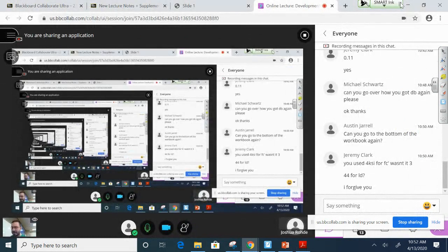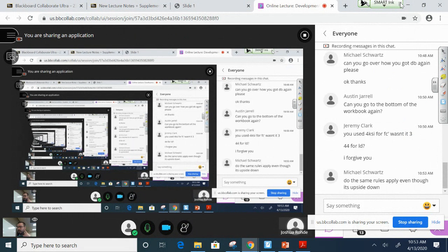What we're going to do next time is, as you noticed, we got a development length of 44 inches. That's kind of long. So how can we shorten the development length of a bar? Well, you can bend it. So what's the development length of a hooked bar? That's what we're going to talk about on Wednesday.